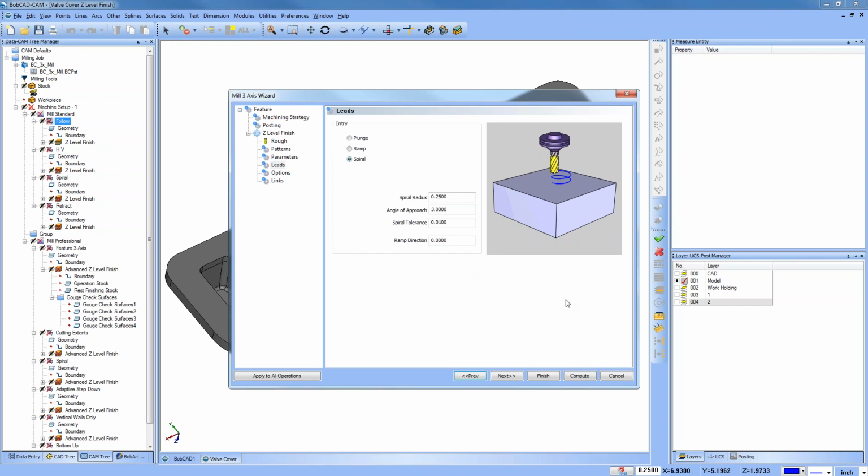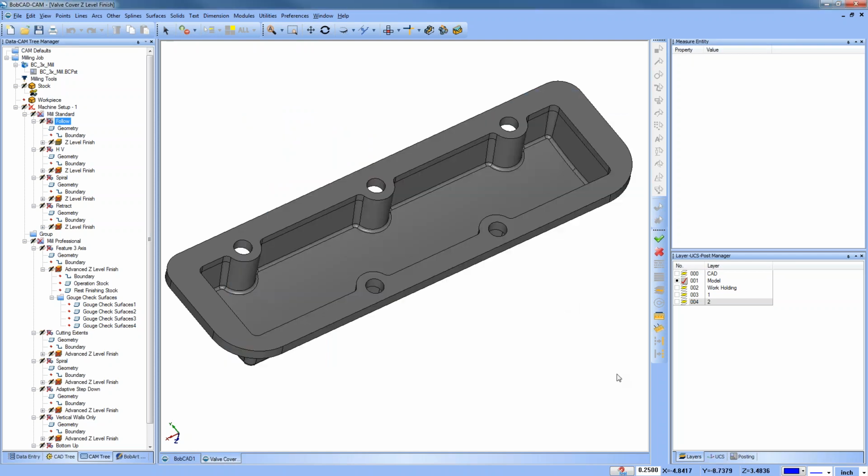A question did come in. I think I was told by tech support that loading an STL file, I cannot extract edges because it is triangle geometry, so why would I save my stock as an STL? Great question, Mark. You'd save your stock as an STL so that you have the in-process stock. And tech support was correct. You cannot create edges or wireframe off an STL because it's a triangulated mesh.